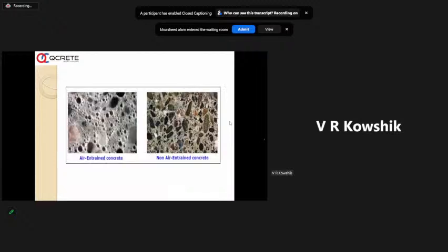You can see air entrained and non-air entrained concrete. Earlier, even in India, many of the projects, even though they were not in the cold zone, used air entraining admixture to make a cohesive mix when sands were not good, when sands were harsh, having ungraded particles, to reduce bleeding and make a cohesive mix, especially at dam sites where you are using big aggregates, 40, 80, 150 mm.